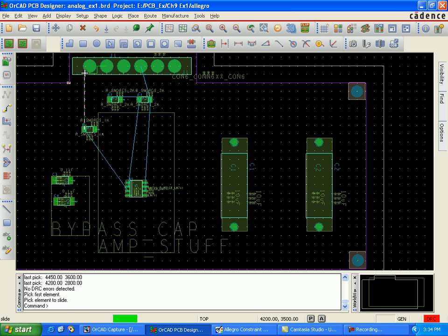Select the blue lines, which are the connections, but as you know there has to be perfect geometry for the routes in order to move the track for the PCB, which is also important because of removing crosstalk, impedance, noise calculation, frequency, all this matters. So we have to do perfect routing.